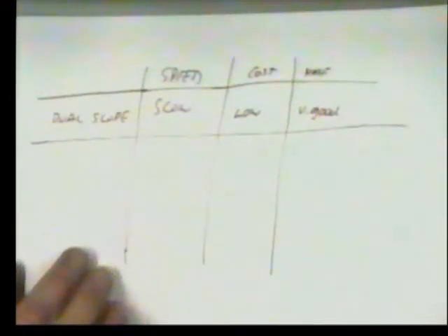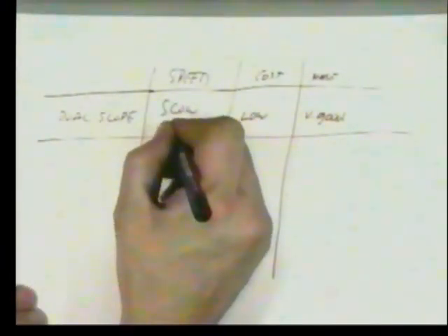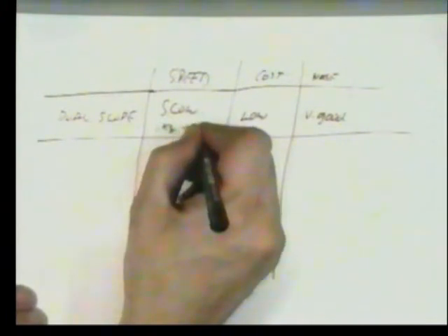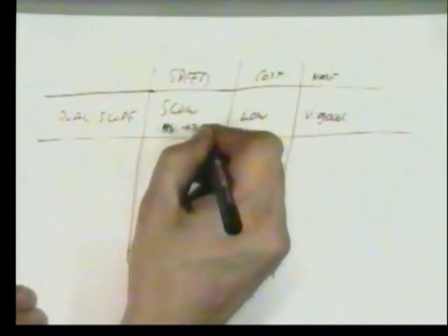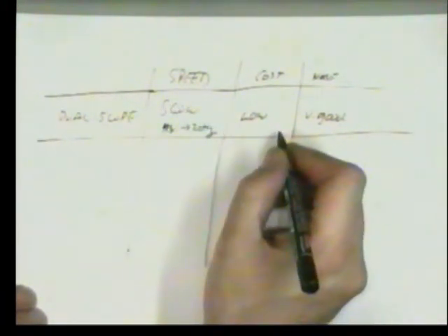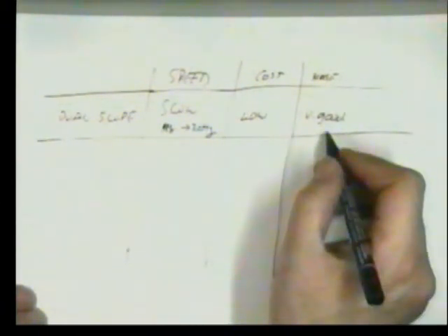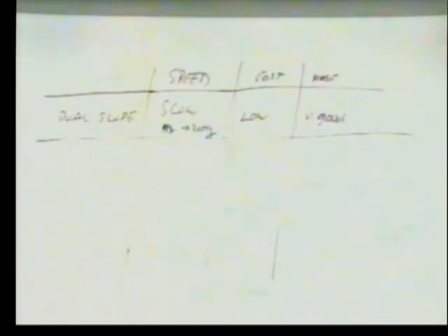So we have an ADC that's slow, typically 1 hertz to say 30 hertz maximum. Cost is low, it's quite cheap. Very good noise immunity. What if we need to go faster? I mean, that's going to do for most simple domestic systems. It's not going to work for a car. You need something that's a bit faster than that.